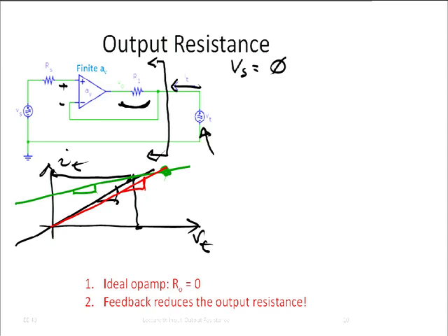You would have to vary along this point here and then figure out the incremental slope. Then you still could get the right answer. But if you simply divide the two values, then that's true only if your characteristic goes through zero. And how do we make it go through zero? Well, in a linear circuit, you can do that easily. Turn off all the sources. Okay? So that's really the deal behind it.